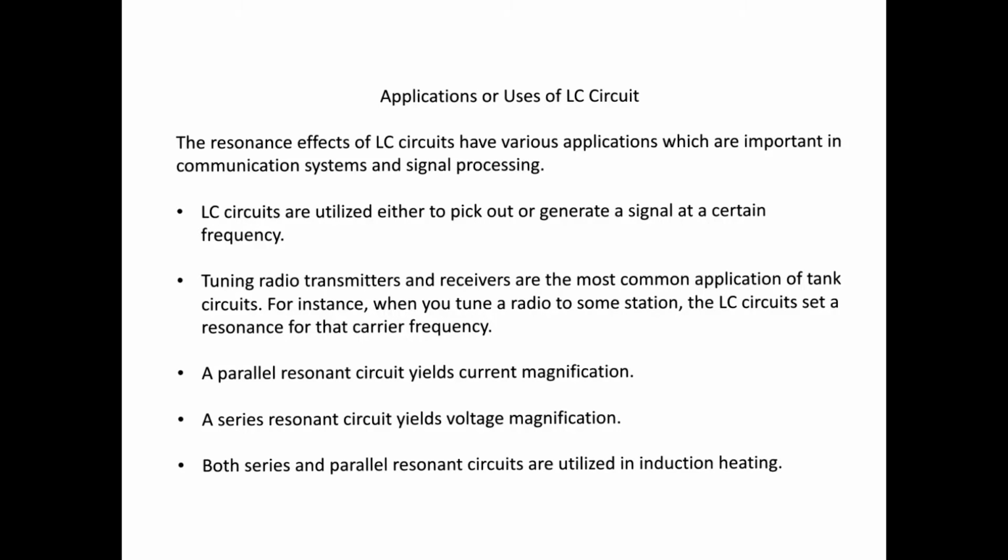For the applications or uses of the LC circuit, we have signal processing. LC circuits are utilized either to pick out or generate a signal at a certain frequency. It is also used for tuning radio transmitters and receivers, the most common application of tank circuits. For instance, when you tune a radio to some station, the LC circuit sets a resonance for the carrier frequency.